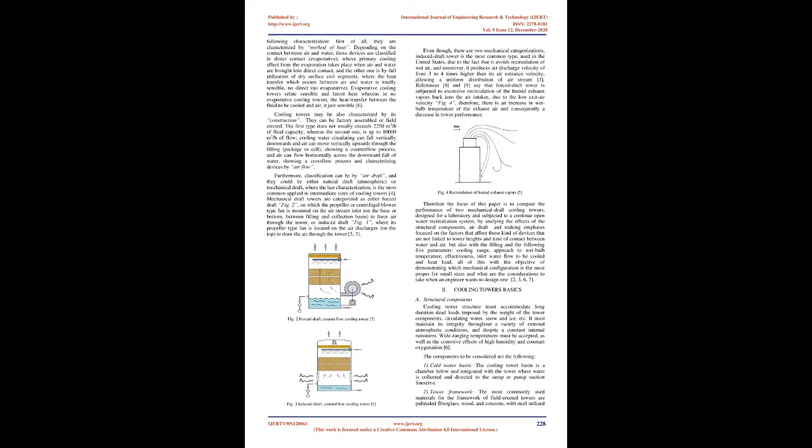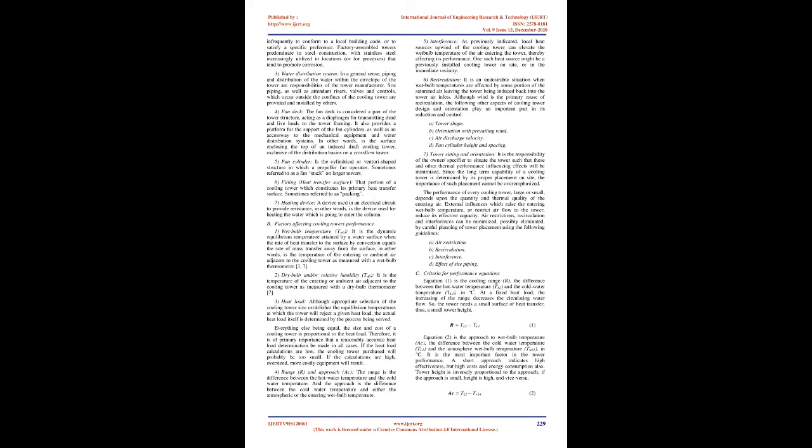approach to wet bulb temperature, effectiveness, inlet water flow to be cooled, and heat load, all of this with the objective of demonstrating which mechanical configuration is the most proper for small sizes and what are the considerations to take when an engineer wants to design.